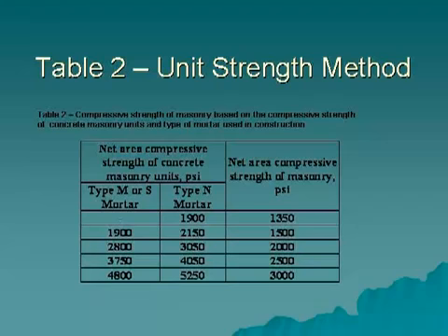How does an engineer or designer know what the block strength is, and if it is in compliance with ASTM C90 or the strength specifications? Initially, it is confirmed by a test report provided to the contractor by the block manufacturer before the job is started.